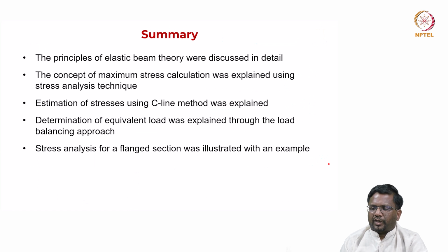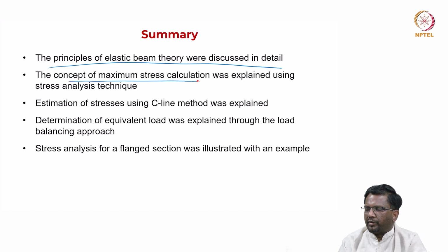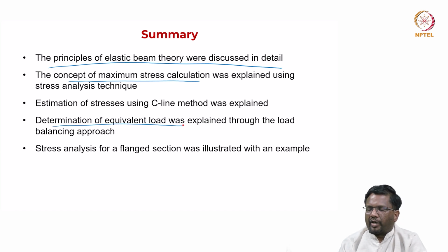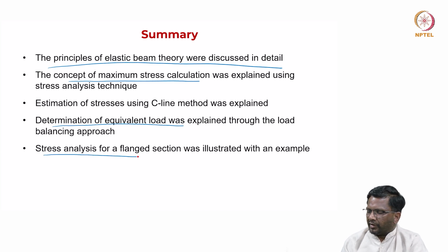Let us summarize what we have discussed. We discussed the principles of elastic beam theory, and we used three methods of analysis, three concepts: the stress concept, the C-line method or force method, and the load balancing method. We saw different sections and how to calculate the maximum stresses, how to calculate the equivalent load using the load balancing approach, and we also did one example of stress analysis for a flange section.